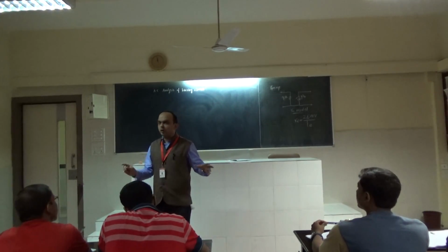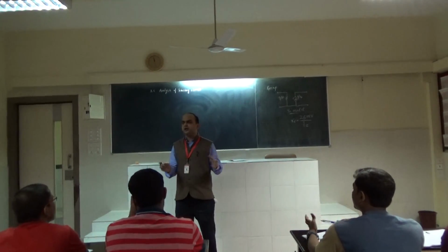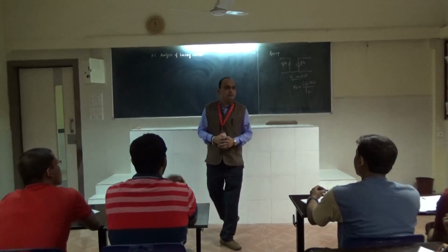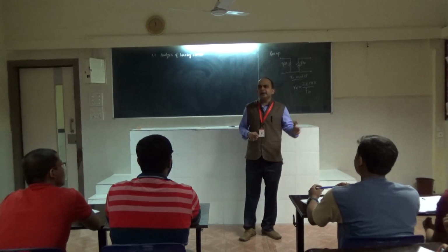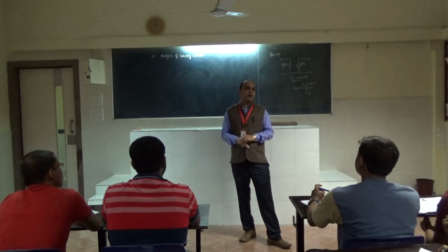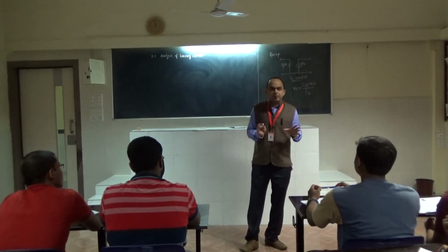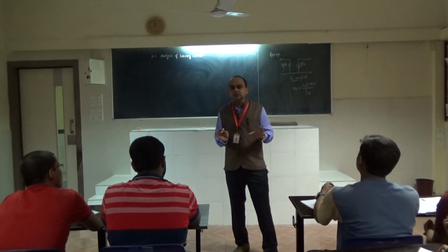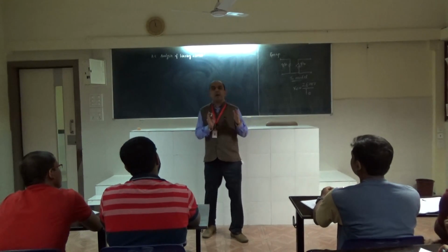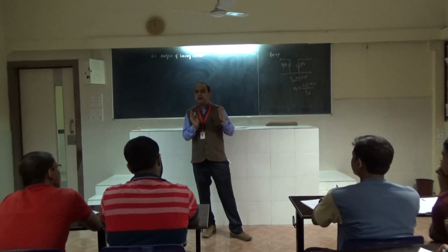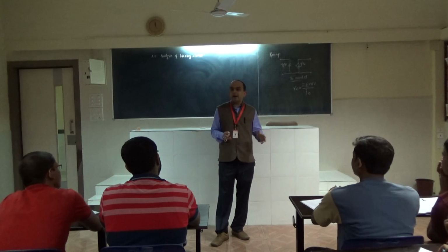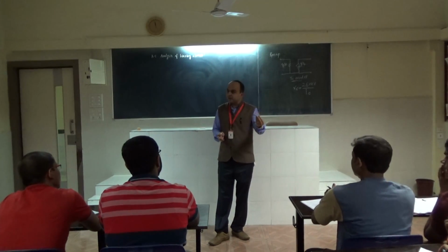Is it not? We have found out IB, we have found out IC. What is the relation between IC and IB? IC is beta times IB. And what is the relation between IE and IB? IE is 1 plus beta times IB. Very nice. So based on this foundation, we are now not going to restrict the circuit diagram just as a biasing circuit. We are going to make it an amplifier. How will we make it an amplifier? By giving some input. There will be some AC input.